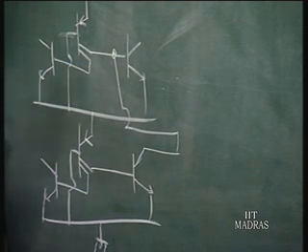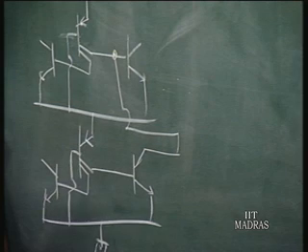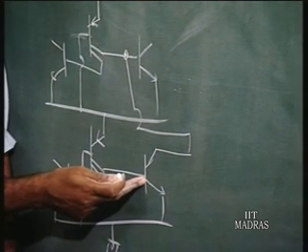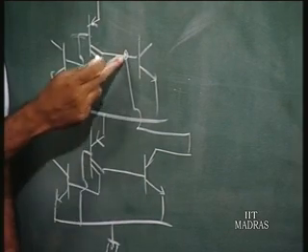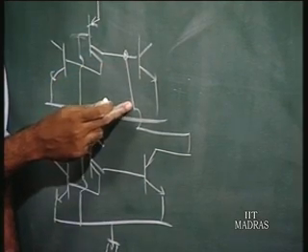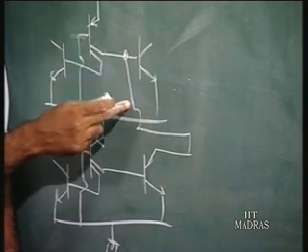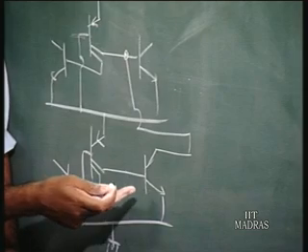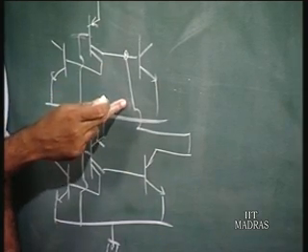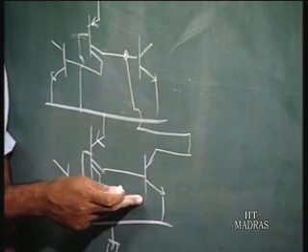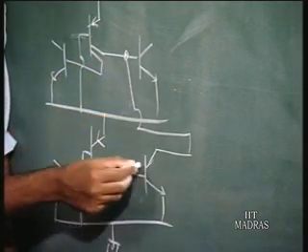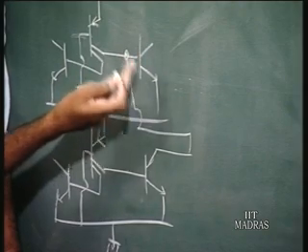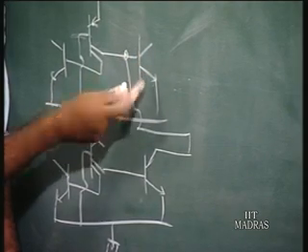is not necessary, you can do it directly, because if this transistor is cut off, then this is not drawing any current. The basic idea is that when this transistor is cut off, it should not draw a current, and this current source current will turn on this transistor. So there is no problem. When this transistor goes to saturation, current will flow in here, and the upper level transistor here is not going to go to saturation, it is going to be cut off, no problem.